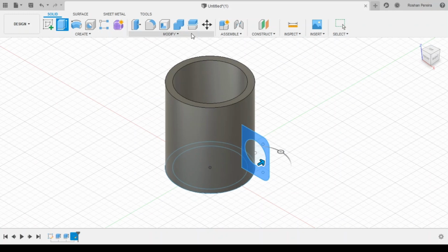Now you remember I told you about the direction wherein you only do the extrusion on one side. In this you will do the extrusion on two sides. The direction will be for both sides. So I click here, instead of one side I click here two sides. Now whatever measurement I put here will be applicable to both sides by default. I'll give you an example. I'll put 2 mm. So the total width will be 4 mm, because it will be 2 mm there. Now the arrow that's selected is extruding on the right hand side. And on the left hand side I want to also extrude 2 mm.